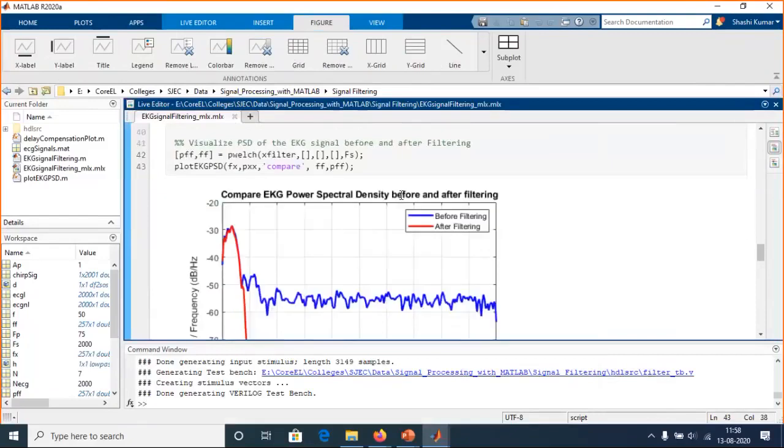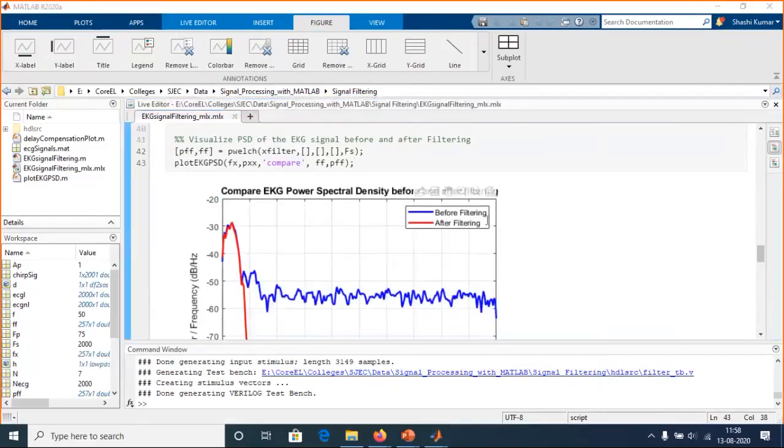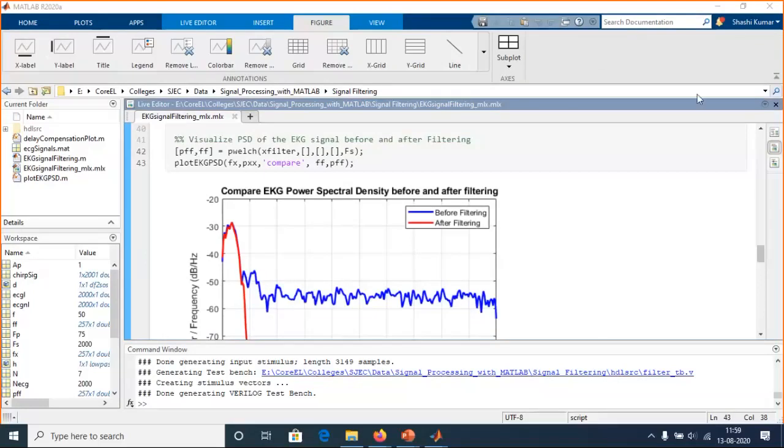All right, just for students' clarity: we have taken the toolbox and seen the different filters. We could compare them, and we also exported to Simulink, and we have seen that, right? Now we also know that we can generate MATLAB code. The clarity I wanted to ask about is that what we generate from the tool is a function, right? That function can be used as a filter function, where the input signal can be taken and filtered, and an output can be taken.